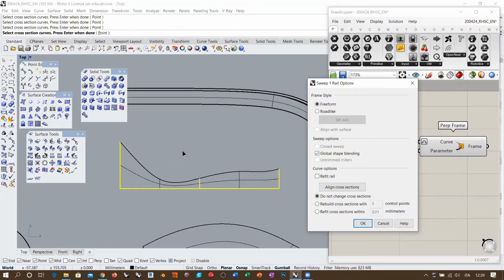So it is actually behaving more like a straight interpolation, like from here, I must go through this point, but then I must also, let's say, raise up once again, because the third point is up here. And so I need to prepare somehow, go lower, and then run towards this direction here. So you see that the free edge of the sweep one rail is very difficult to control, also when you have this kind of very irregular situation here.